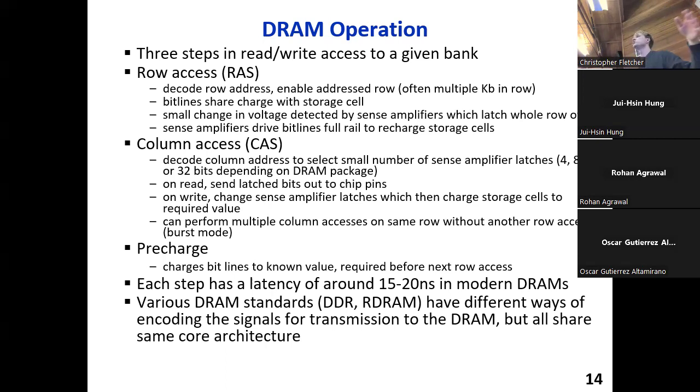There's some residual amount of charge left over on the bit lines. This goes back to the principle of DRAM. It's designed to be extremely dense. These capacitors are relatively weak. So the potential difference that happens when you open the access transistors and dump the charge out is extremely slight, with very slight variations on the bit lines, and it doesn't all get sucked out at the end of the operation.